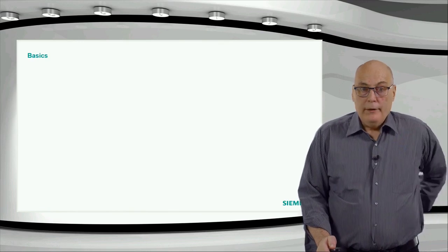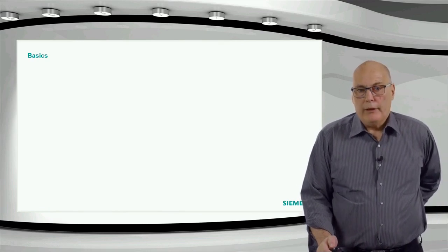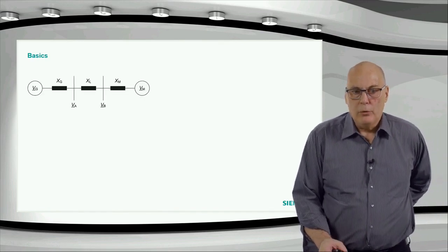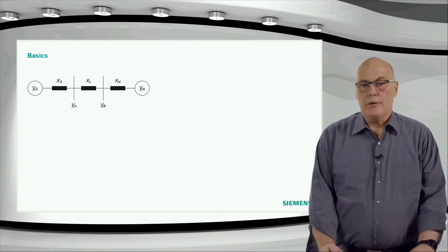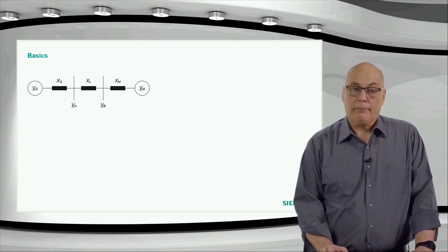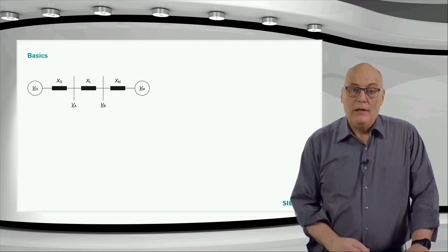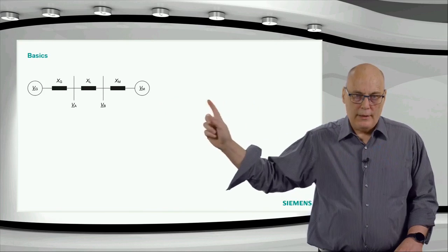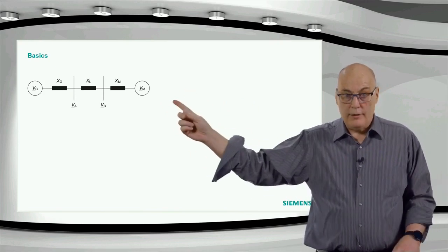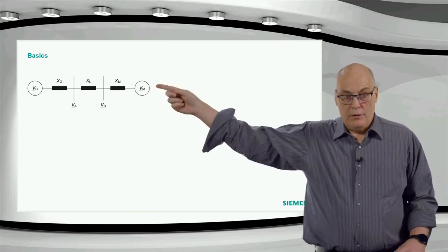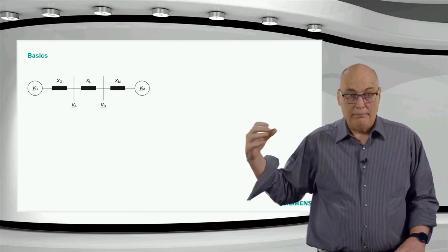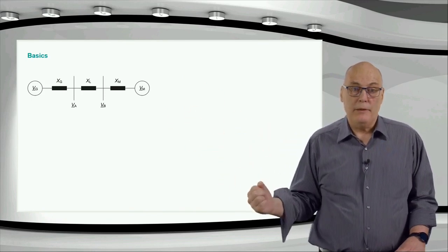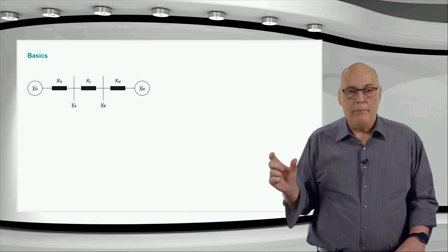The power swing blocking is something where we again look at the system, and we're going to use a model. The model we're going to use is a so-called two-machine model. In this case, a lossless two-machine model, where we have a generation on the one side and a motor or load on the other side. And in between, obviously on the generation side, you have a generation impedance, source impedance. Then you have the XL, the line impedance.